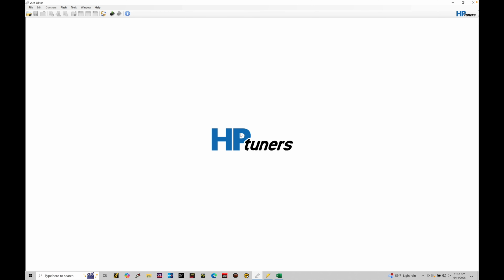Luckily, HP Tuners has provided us a speed density calculator, which is going to be greatly simplifying the calibrating and tuning of our individual speed density tables. Previous to the calculator being available in the HP Tuner software, we would have to go in and edit the slope, which is one of the speed density terms within the speed density model with an F-150.